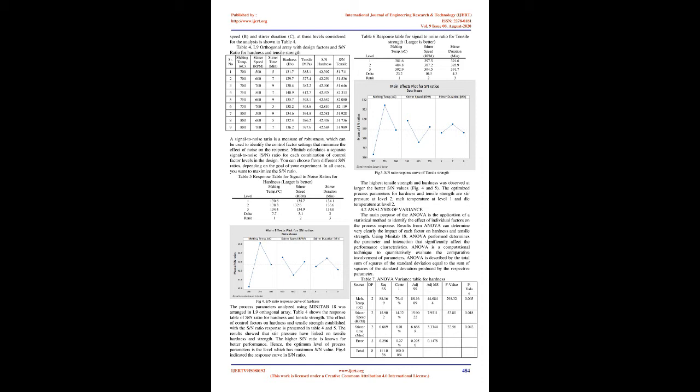3.1 Materials Characterizations. Fig. 2 indicates the tensile evaluation samples that are machined from fabricated rods. The samples were fabricated according to Taguchi orthogonal array, and the tensile and hardness were examined. The hardness was tested at 3 different locations and the average value is taken for the analysis. The tensile test specimens were prepared and machined from the casting. The tensile tests were completed with the specimen in the universal testing machine at room temperature.